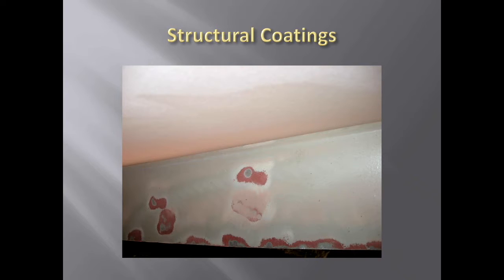This is a typical overcoating system. You can see the red lead actually on that. The specification requires that any areas that are peeling or lifting have to be sanded off and faired out. And what you can see here is the painters have gone in and sanded this down and then faired it back so it's smooth and it's not lifting.